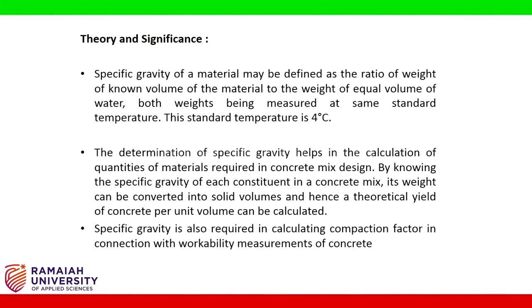The determination of specific gravity helps in the calculation of quantities of materials required in concrete mix design. By knowing the specific gravity of each constituent in a concrete mix, its weight can be converted into solid volumes and hence a theoretical yield of concrete per unit volume can be calculated. Specific gravity is also required in calculating compaction factor in connection with workability measurements of concrete.